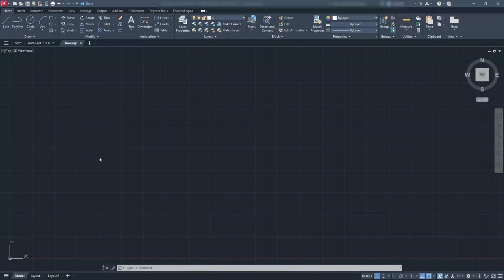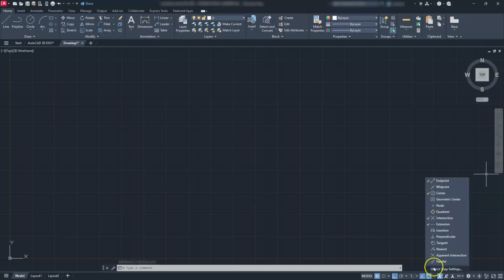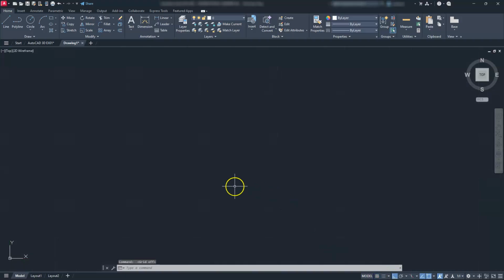and this will work just totally fine for us, because remember, one of the shortcuts that you can always use is if you start spelling out the command, or if you know the command that you want to use, it's a lot easier to find exactly what command you're looking for just by spelling it out. So I'm going to purposely leave my ribbon the way it is right now. I will go ahead and turn the ortho on right now. Some of the other things we're going to do, let's see what running O-snaps I do have on. And I will turn on the quadrant one. And then I'm going to turn this pesky grid off because I don't like using it. Alright, so that should be everything that I need.